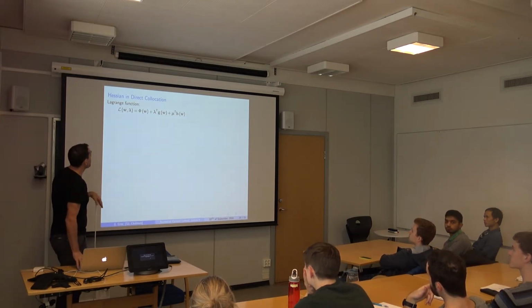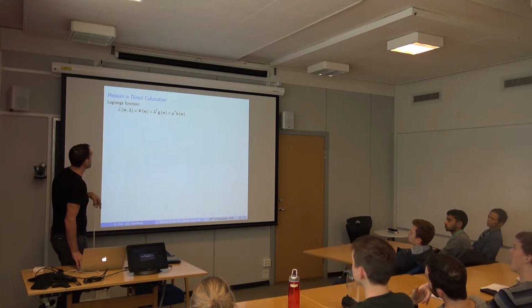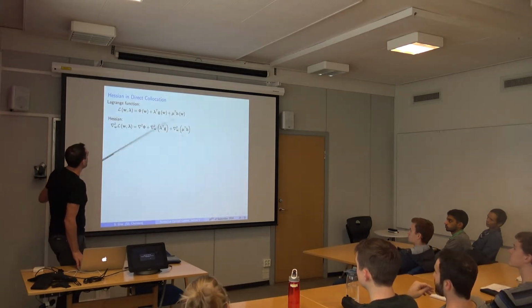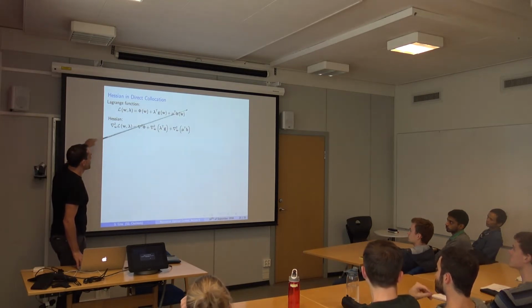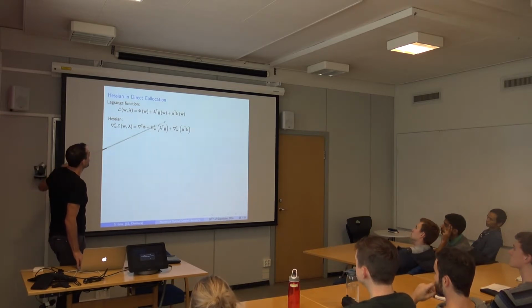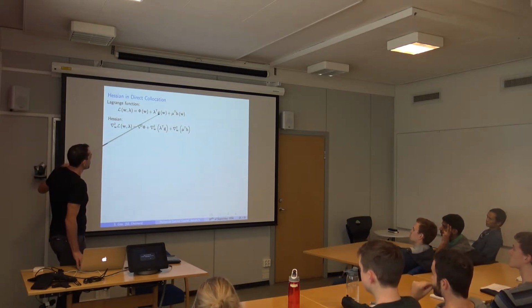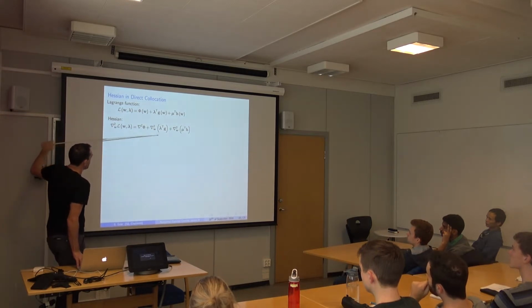It turns out that if you use direct collocation, it's actually trivial to compute the Hessian of the Lagrange function. I can show you why quite easily. So again, the Lagrange function would be made of that. This would typically have the right structure, so that's not a problem. That's easy to compute. The problem is in the equality constraints where you have all the dynamics, and when you compute the Hessian, you have to compute these terms here, and especially this one that is very expensive to compute in multiple shooting.